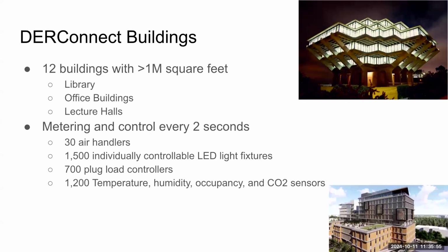We're not using OpenADR in any of these because it was too late for us to make it part of it. But it's a bit of a challenge, though not insurmountable. Many people use the APIs for lighting controls, so it's definitely doable. You just have to spend some time to make it work. Most things in buildings are BACnet, so that's the main workhorse, I would say, for communications with most of these devices.